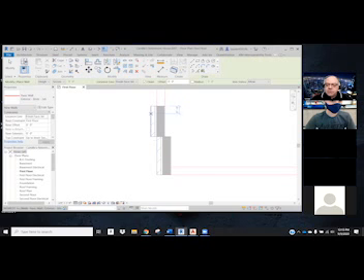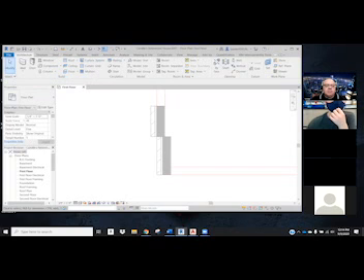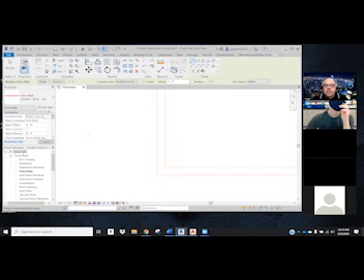And now we want to make sure we draw it correctly. So I wanted you to see the difference between finished face exterior and finished face interior for an exterior wall. You need to be aware of that, because you're going to make some mistakes. So I'm going to go ahead and use the modify tool, select each wall, and then delete them out, so I can go back into my wall again and draw them correctly. I'm going to grab that endpoint and then draw off my interior finish face.